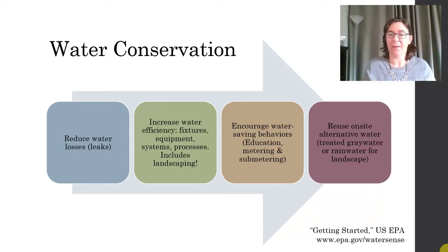Ways to save water. But as an architect and designer, you can also help this activity by providing water metering and sub-metering for the different water processes in your building. There's a saying, you can't fix it until you can measure it. By providing this sub-metering function, you provide a way for somebody to judge how much water they're actually using and therefore some ways to improve.